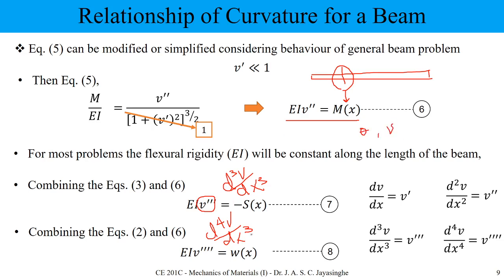Otherwise, if you know the shear force, or the main way of using this, you can start from here. If you know the load intensity, then you can apply the load intensity here and replace it, and you need to end up with integration. The first integration gives the shear force, the second the bending moment, the third the rotation, and the fourth the deflection.